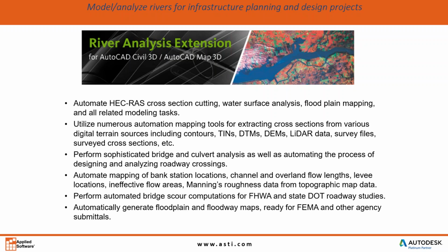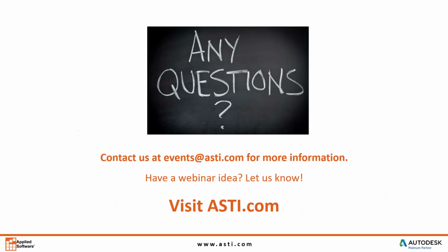And then floodplain, generating flood maps. Clearly, you want to be able to utilize the data from Civil 3D in terms of flood maps and be able to edit and model those in a program such as HEC-RAS. So there's an extension that allows you to push data straight from Civil 3D into HEC-RAS, and the river analysis would be one of them.